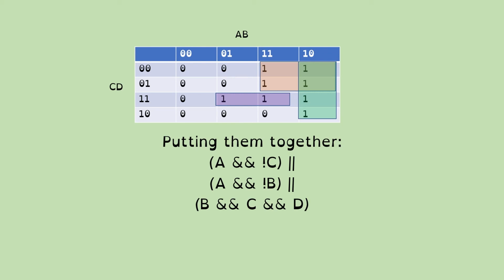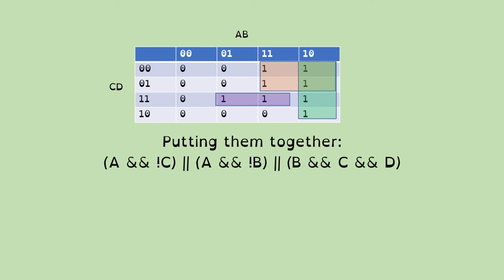It's a bit like doing the truth table as a whole, where you take every line that gives you a 1 output and get the Boolean expression for that line, except instead of doing individual lines, we're doing it in regions, so it reduces the complexity. That is probably as far as we can reduce, and it's certainly a reasonable reduction of this particular example.